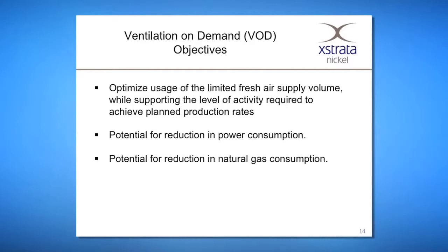And because we're in a northern climate in the winter, we actually have to heat our air that we pump into the mine, otherwise we'll end up freezing the shaft up. And we heat that air with natural gas, so there's an obvious benefit: you reduce the volume of air, you reduce the volume of natural gas consumed.